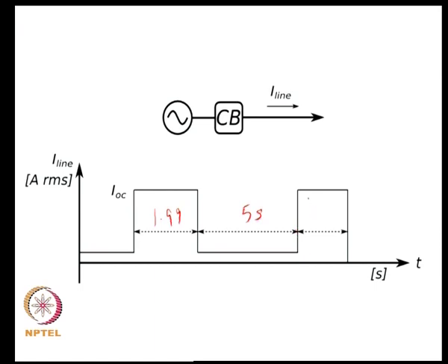Now, if your overcurrent level went up to a higher level, it would need a full 2 seconds to trip again. Okay. So, depending on your calculated trip time and your reset time, you could evaluate for what duration your circuit breaker would need to operate with devices such as reclosers, where your current level can potentially go high and low.